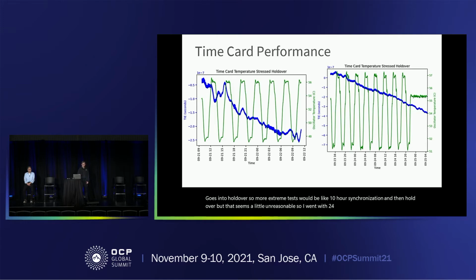As you can see from the graphs here, the left axis is the time interval error. Actually, on the scale that it's on, over 3 days, it didn't go below 500 nanoseconds. So that gave good confidence that our current reference architecture and current oscillator design is able to give us the 1 microsecond over 24 hours at normal data center operation.